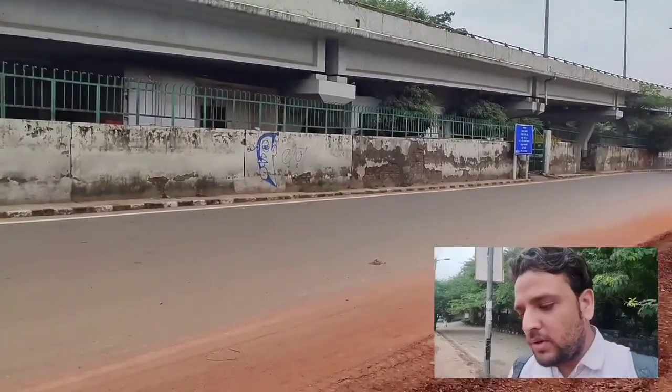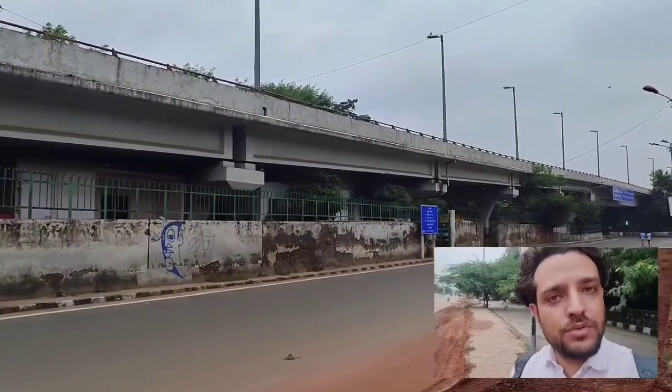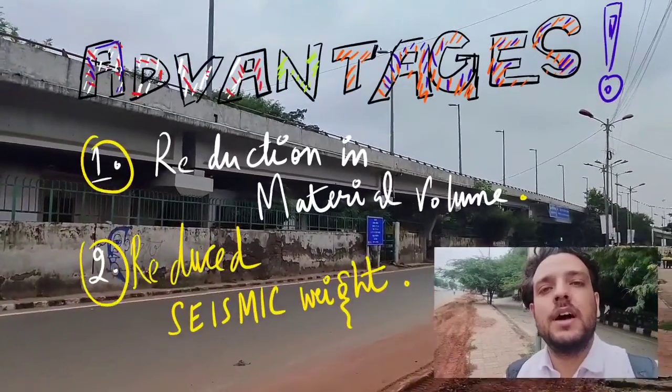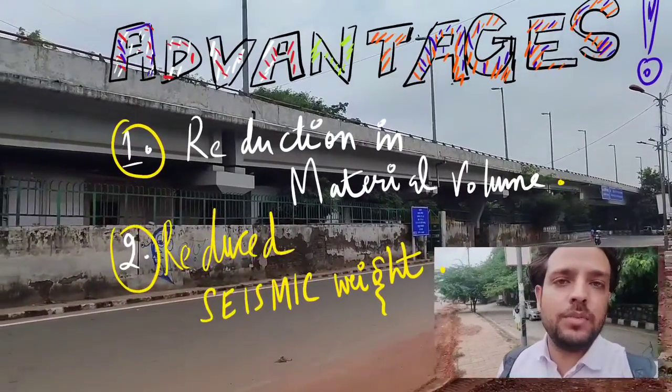Another thing to be noted is that by designing your superstructure with flanged beams, your total self-weight will be reduced, and once it is reduced, we know seismic forces are inertial forces. The effect of seismic forces depends upon the mass, so that will also be reduced.